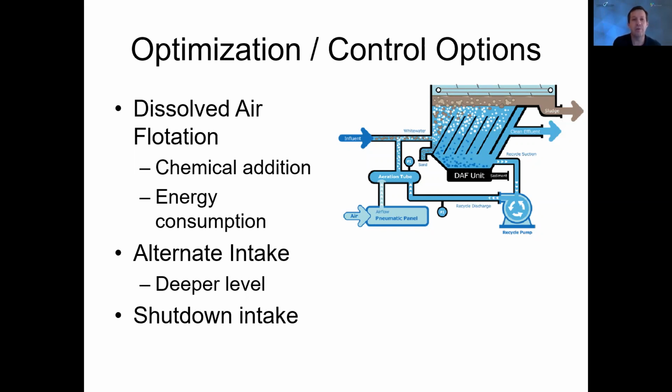So that's why they're called dissolved air flotation cells, because the oil droplets are so small that they are actually considered to be dissolved within the process. And when they get inside the separator, they start to coalesce, they bump into each other, they form larger droplets, they bump into the oil, they bump into the algae, they form larger particles. And the larger the particle, the easier it is to float. And eventually it's all skimmed off and removed.